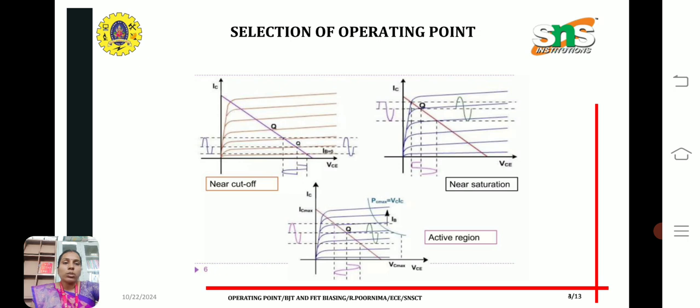So for the transistor to act perfectly as an amplifier, we need to stabilize the operating point in the center of the load line, that is, in the active region. This is the main reason for choosing the operating point in the middle of the transistor load line.